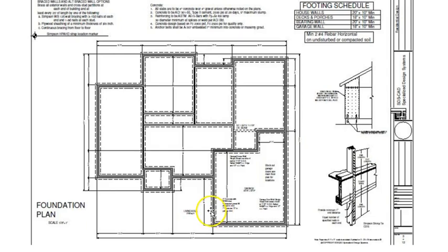So here we see what appears to be a house, and these dark walls would be the foundation walls most likely, and the dashed lines on both sides would be the footings that are larger than them, but they are beyond sight in this plan. They're kind of out of view, so to speak, but we can see that all of these bearing walls do have footings below them. That's why we have continuous dashed lines following the dark walls.